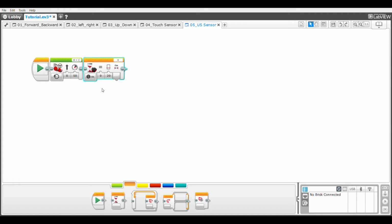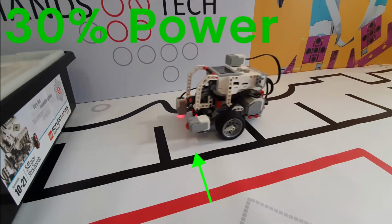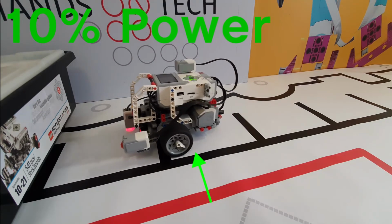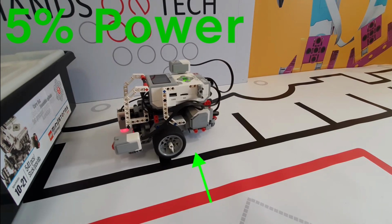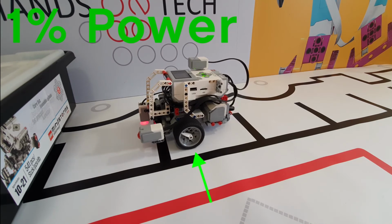If I do choose equal to, this is what happens at different speeds. The green line represents 20 centimeters away from the object. You can see the robot is never actually stopping where it's supposed to stop. This is because the sensor never actually sees exactly 20 centimeters. Even on 1% power, it doesn't manage to find it.